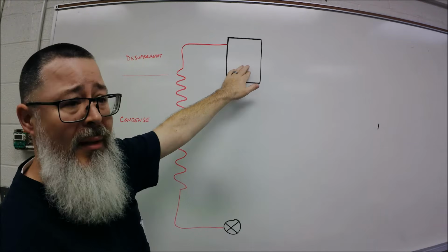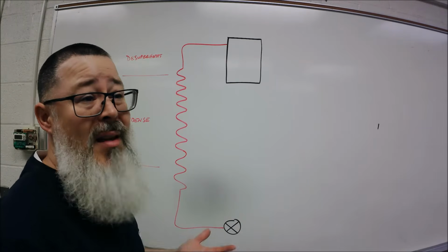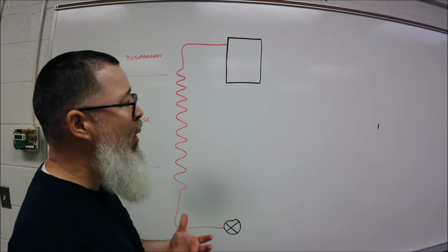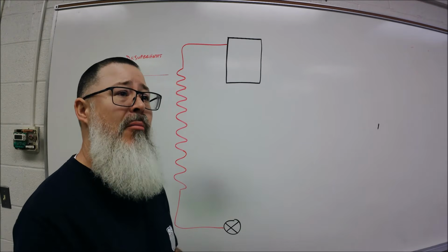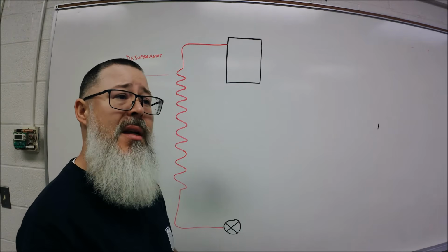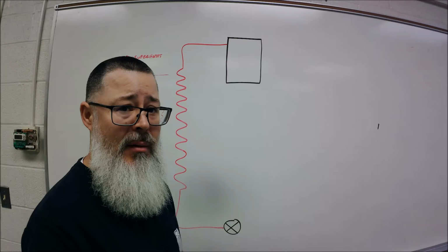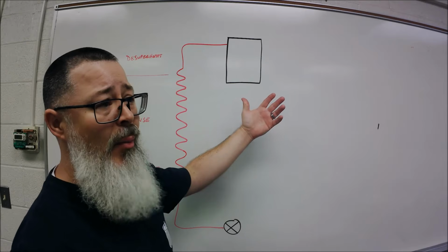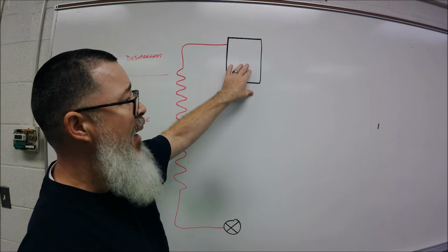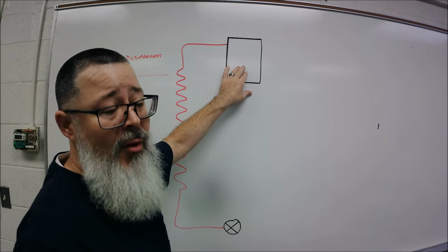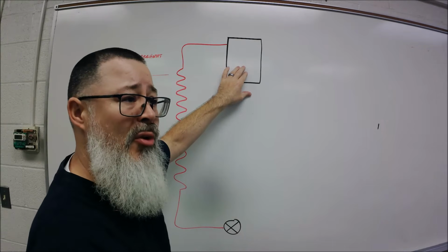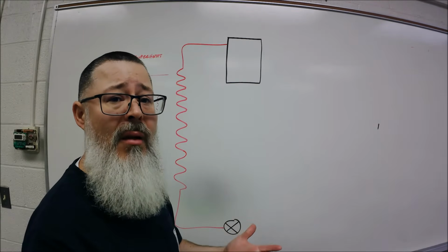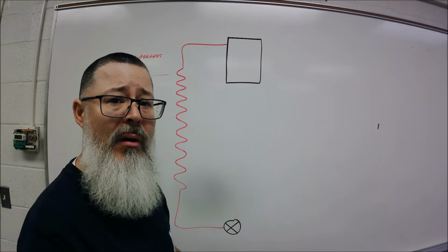So once we get that superheated vapor off of the low side, it may be 50 degrees or 60 degrees. A lot of people think that's very cold, very cool, and it is. But by definition, superheat is heat above a saturation point. Doesn't matter the temperature. It's the definition of it. So we've got maybe a 50-degree refrigerant vapor going in our compressor, and the way I like to think about it, just to get people started: what keeps that sealed compressor cool? The refrigerant vapor that's passing over it, right? It's absorbing the heat from that motor, right?